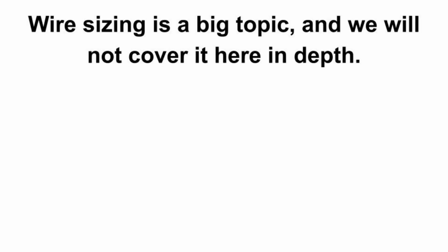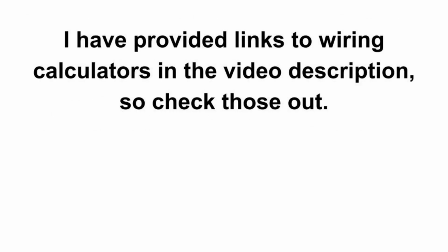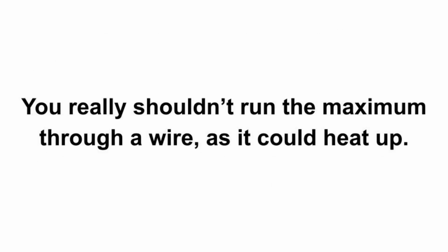Wire sizing is a big topic, and we will not cover it here in depth. I would encourage you to research more about wire sizing before wiring your battery bank to ensure you are creating a safe emergency backup power. I have provided links to wiring calculators in the video description, so check those out. And as a rule of thumb, use at least the next larger size wire than you need. You really shouldn't run the maximum through a wire, as it could heat up.